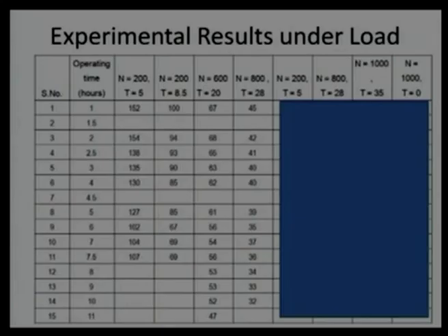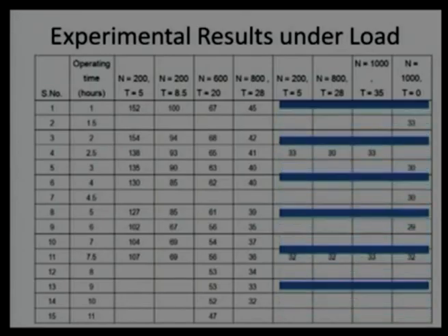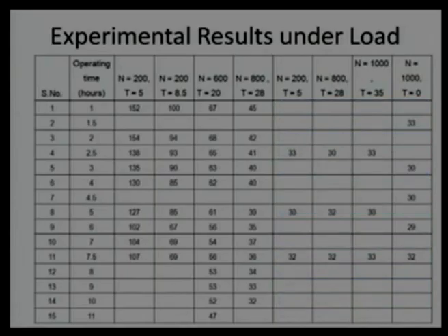whatever we are thinking, the vibration is creating some problem, a pitting failure or related failure of the related wear because of that is happening over here. Now, if we increase the speed and the torque, again we are getting a lesser number of ppm. Same results for the 800 also. At 800 and load on the higher side at 20 Newton meter, it comes to 32 ppm. That is showing that bedding in time is coming to a closer or almost negligible level.